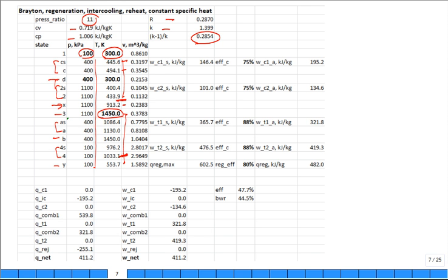Okay? But I do it in kind of a step. I calculate the isentropic work. I'm given the efficiency of the first compressor stage. I calculate the actual work of the first compressor, and I use that information to then get the temperature here. I then compute all of the Q's for each component and all of the works. Some of them are ridiculous, but here is the Q for the first compressor.